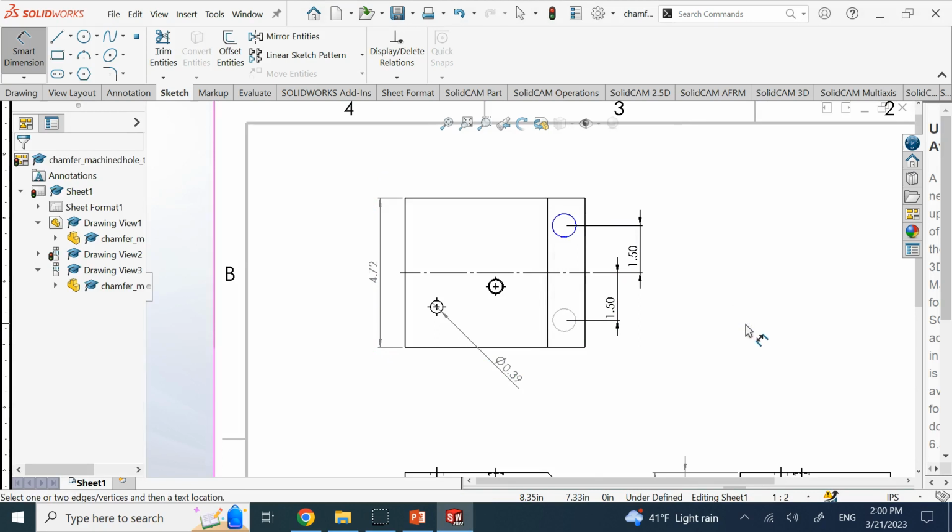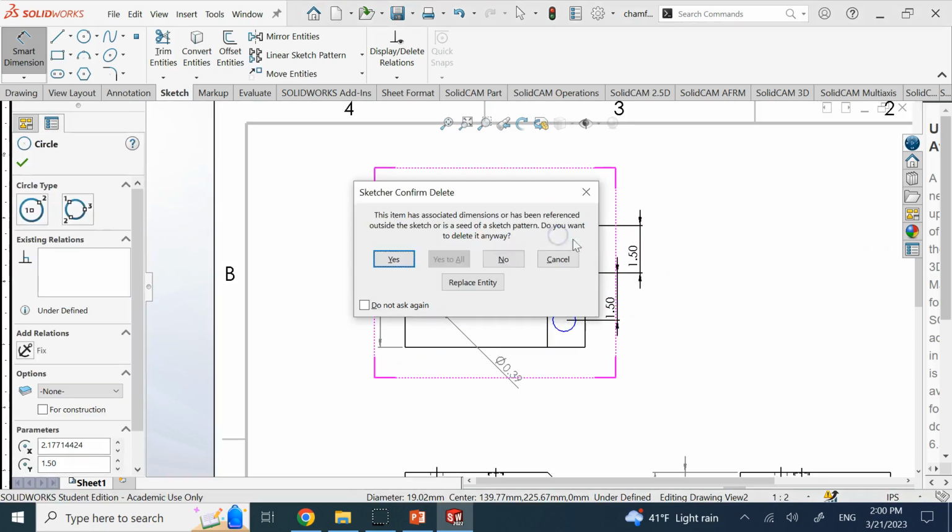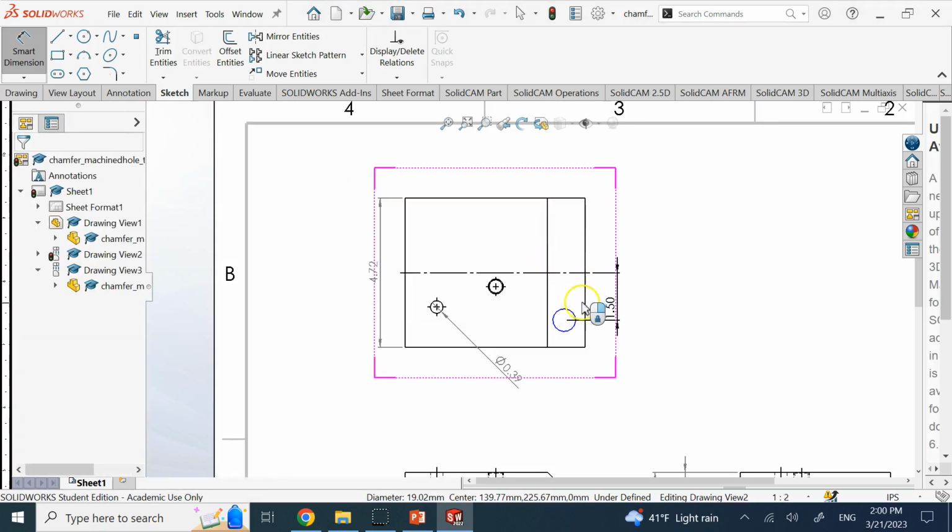Okay, that's the meaning of symmetry. If I have symmetry, I have one number on one side of the symmetry line. I'm not going to put the number on the other side. Just one of them is enough. If it's multiple features, I use n times, or I say typical, as I mentioned in one of my earlier videos. You're not going to show both sides. That's the advantage. That's the thing that you use for symmetry. You should not repeat that, okay? So that's a redundancy here.